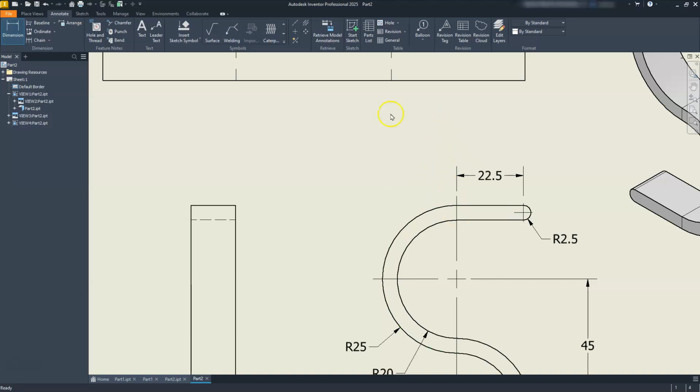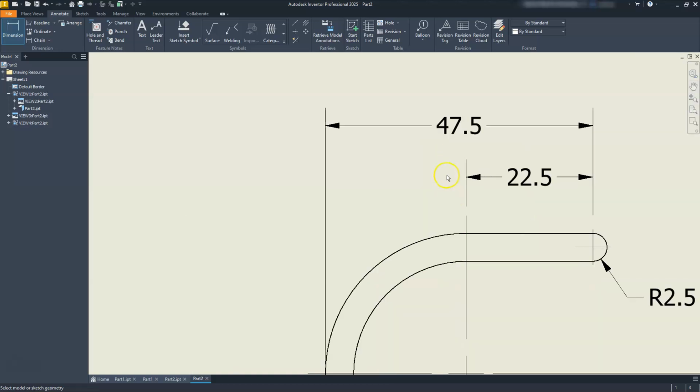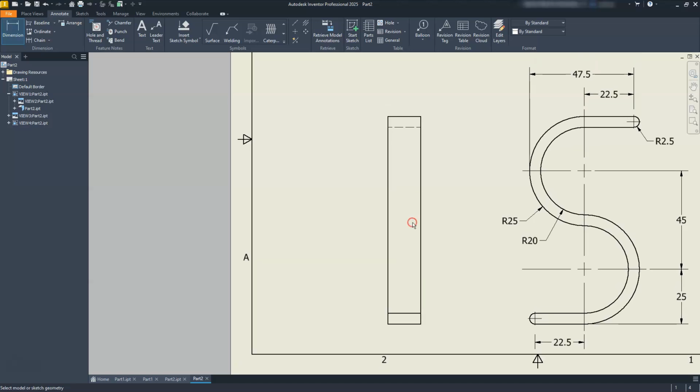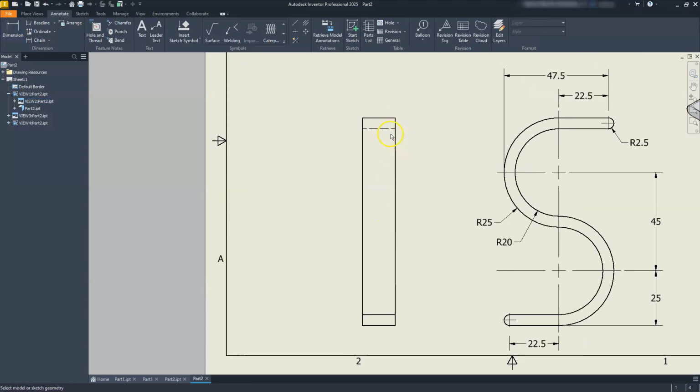That looks like I selected the wrong part. I'm sorry about that. One more time. So from here to that point. There we go. Okay. Let's go ahead and take a look at our right side view here and place some dimensions on it. So I'm going to place that dimension of 15 here. I have one that goes from that line there to this line, set to 95.